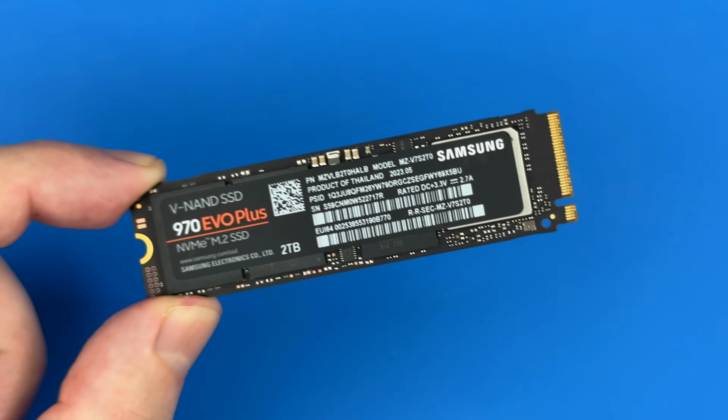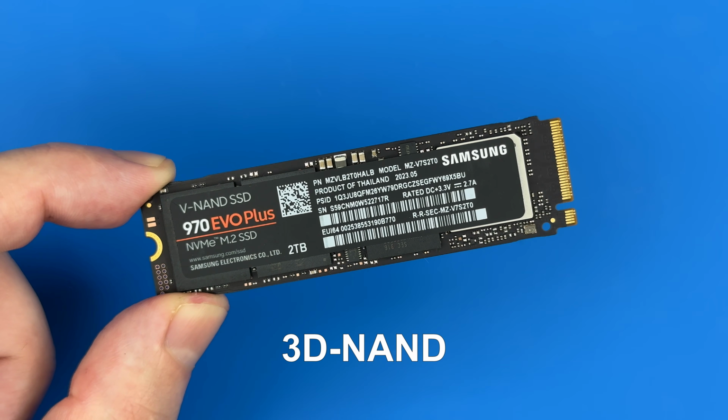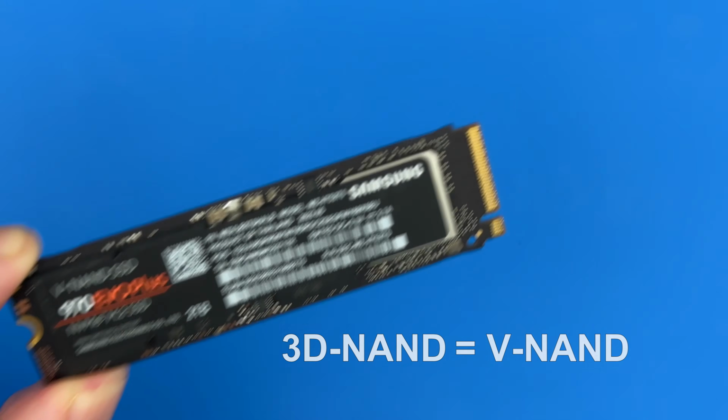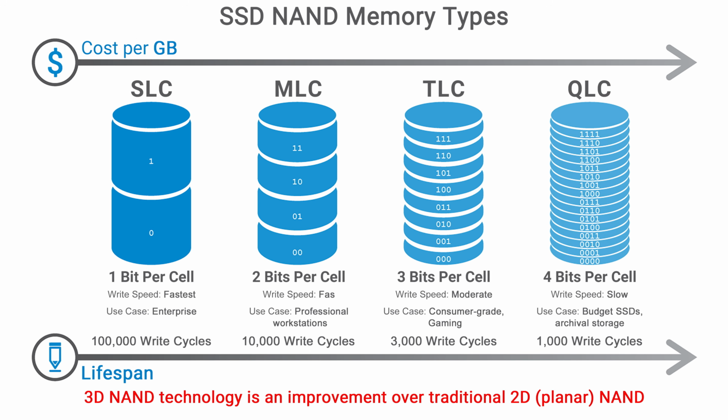In addition to these memory types, there are technologies like V-NAND, vertical NAND, and 3D NAND. While there is no technical difference between the two, V-NAND is Samsung's branding for its 3D NAND technology, whereas other manufacturers, for example Micron, Intel, SK Hynix, use the term 3D NAND. It is important to understand that 3D NAND is not a separate memory type, like SLC, MLC, TLC, or QLC. Instead, it represents an improvement in the physical structure of NAND memory.